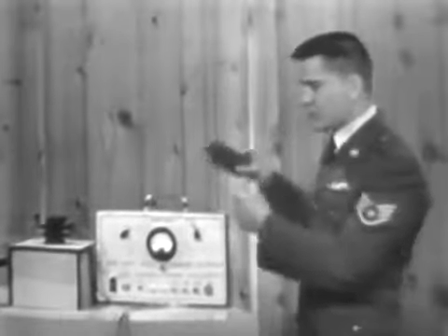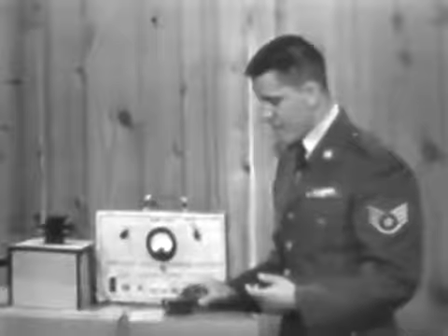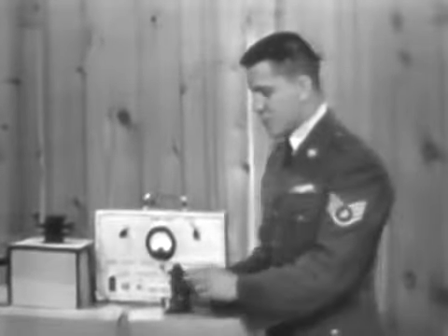Now, two other checks you'll have to perform on transformers quite frequently are those for an open or a shorted winding. Both of these checks can be performed with an ohmmeter. Over here I have two windings identical to the windings we're using in our transformer. One of these windings has 150 turns. Its normal resistance is 10 ohms.